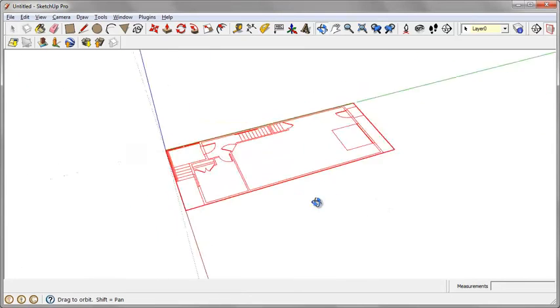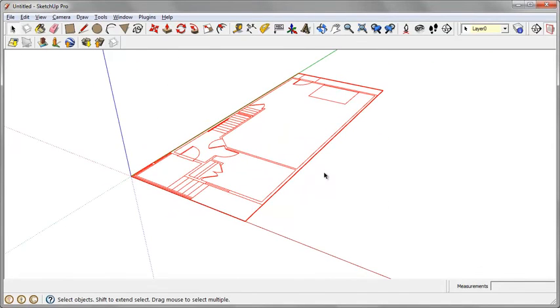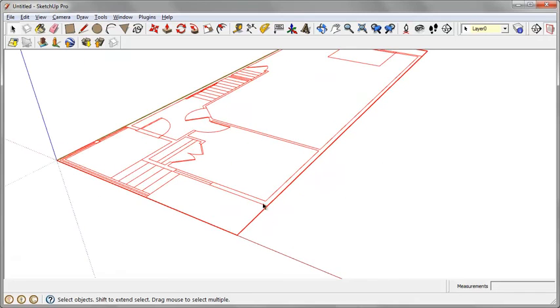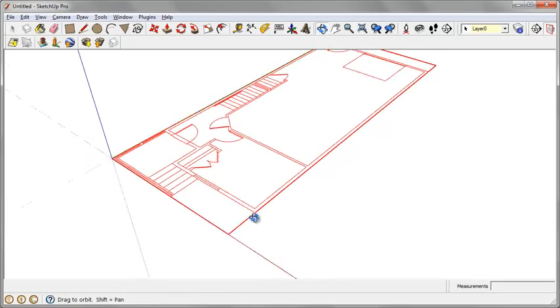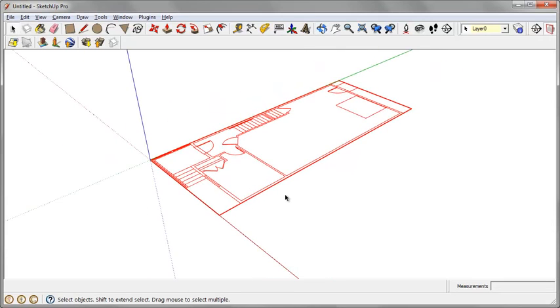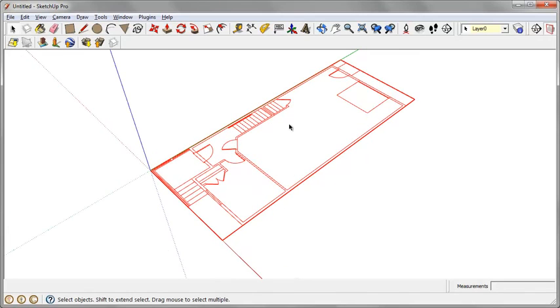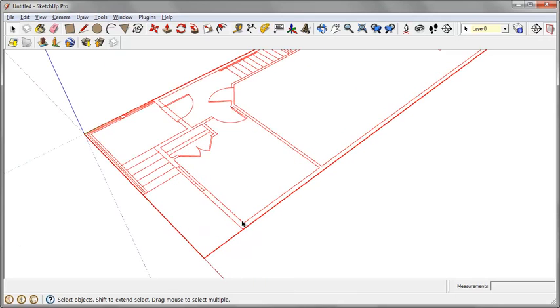Okay, so modeling from this CAD plan, the common tendency would be to want to fill in these surfaces and create surfaces in SketchUp and then extrude it vertically. And there's one big problem with this, and that is that most CAD plans are not perfectly drawn. A lot of people don't adhere to the standards, and they'll just have things kind of off axis and not drawn correctly. Maybe edges don't meet. So typically it's best to just lock that CAD drawing as a background and then basically recreate it. It's really easy to recreate.